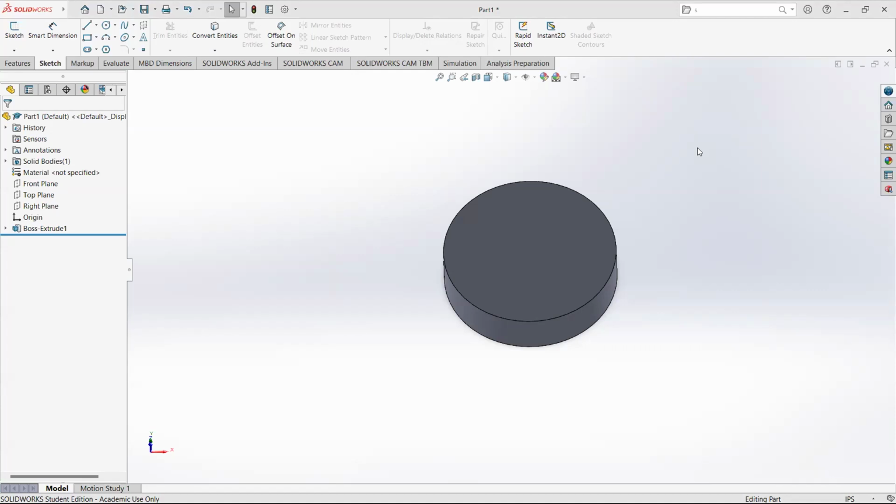In this video, I want to talk all about patterning. We've got a couple of different options for patterning. Patterning is a feature we can add to either sketches or features that basically lets us copy parts in a repeatable pattern. So if we've got a thing with a lot of holes in it, or if we've got to create finger grooves around a thumb screw, something like that, we can use a pattern. We only have to create one sketch or one feature, and then we can pattern it and duplicate it, effectively copy it in a repeatable way.